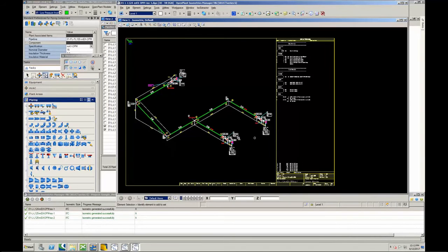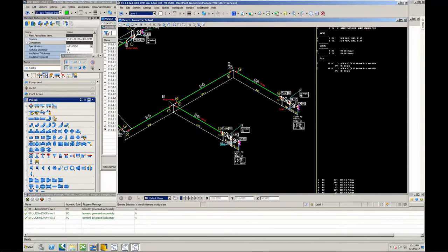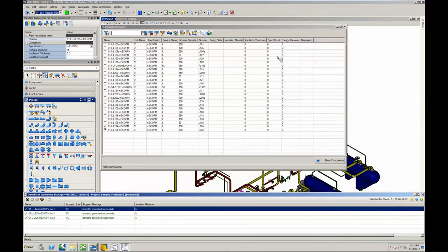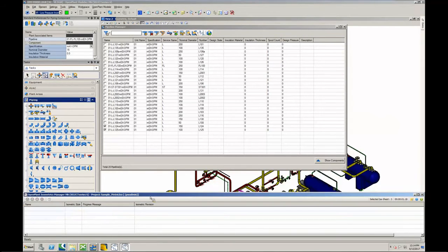Okay, so this looks good. If I hit post all to ProjectWise, everything gets posted, and I have a setting to delete once posted to ProjectWise from this view, so the files are deleted from here.